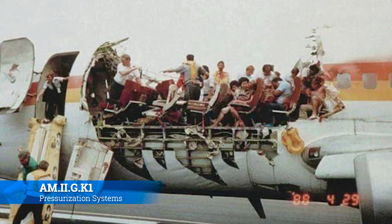So just know that is a factor, that you need to be conscious of the fatigue the aircraft is undergoing as it flies. The older the aircraft gets, the more cycles it has, the more possibility you have of something like this happening. Things aren't going to last forever. Eventually, they have to be maintained, replaced, and so on and so forth. And especially when it comes to pressurization.